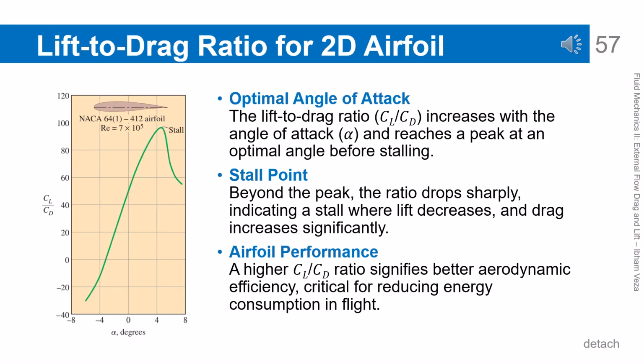Lift-to-drag ratio, variation for a two-dimensional airfoil. The lift-to-drag ratio increases as the angle of attack increases until it reaches a maximum value. This point represents the most aerodynamically efficient operating condition.